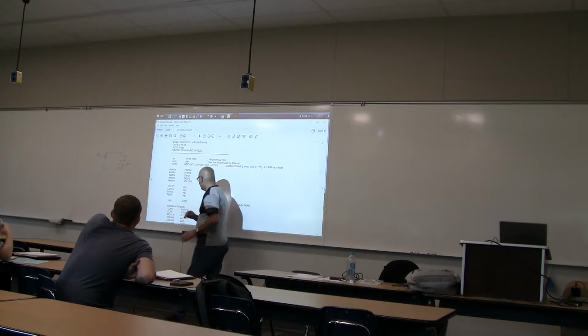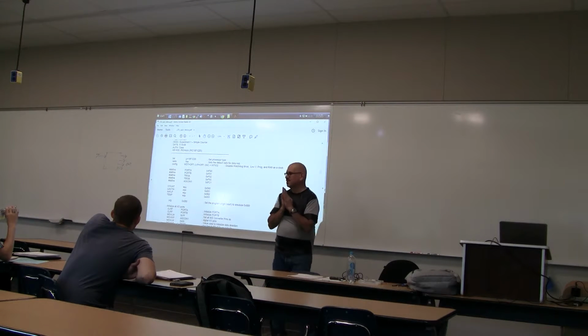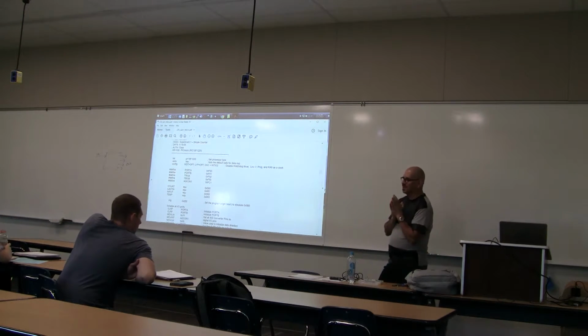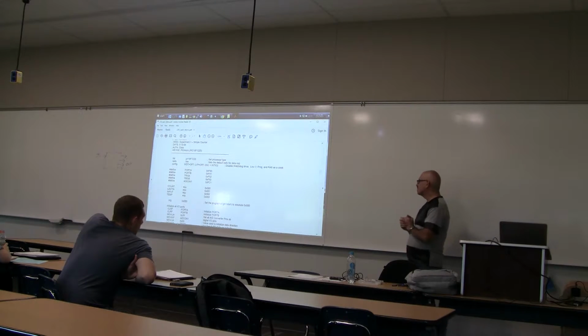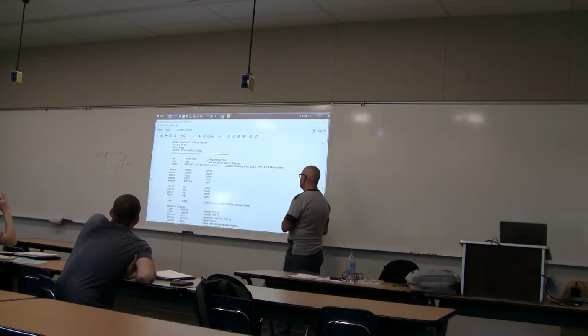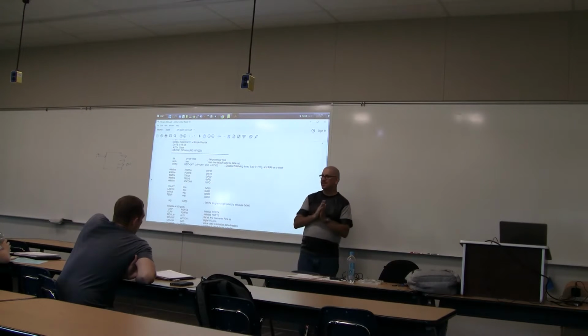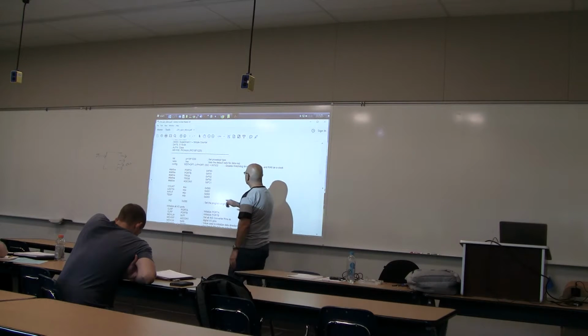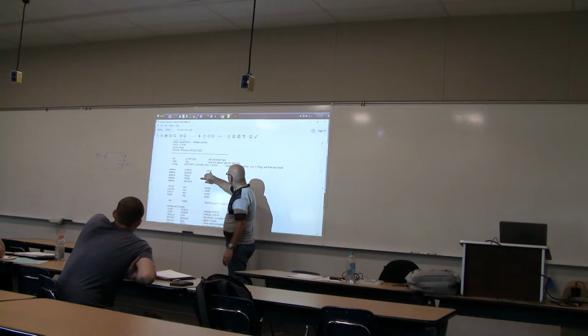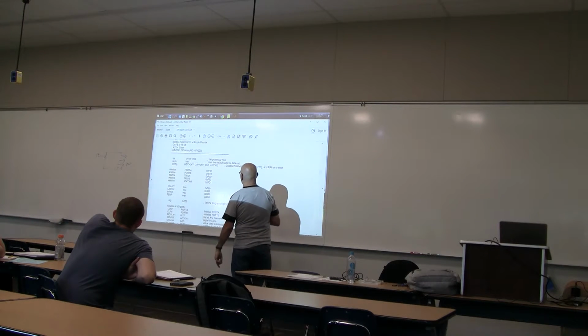Radix hex. We work a lot with binary in assembly language. Why? Because we're dealing with individual bits when we want to control individual pins. So we tend to work and think in binary, but writing out a bunch of ones and zeros is not really useful. But working in decimal is not very good if you're trying to think in binary. So mostly we work in hex. Why? Because if I see F80, I know this is 1111, 1000, 0000. The mapping gets to be really automatic.